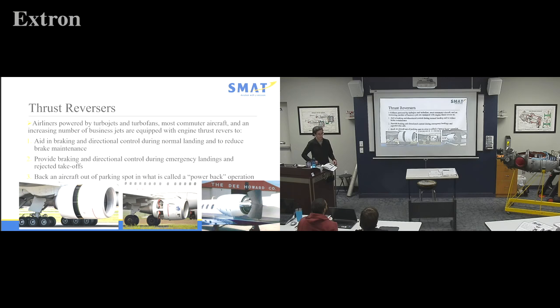Do you think they do that very often, and why or why not? Dangerous, because you can't see who's behind you. That's good. You're directing the airflow down and almost forward, so everything in front is going to get blasted. And what about the engine itself? I don't like that. Exactly what Gavin said. It's going to start sucking up its own exhaust, and that is not good for it. Now you have hot exhaust coming in your inlet, and whatever's on the ground and in the air, it's going to throw gravel and who knows what up into its inlet. So, not used very often.